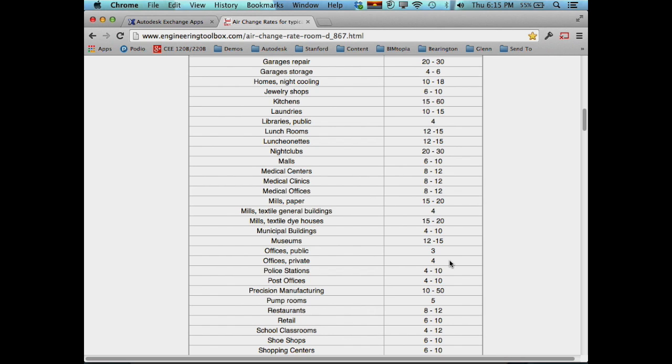You also want to pull away 133 cubic feet per minute. And if everything was super balanced, that would actually work out. It would never be high pressure, it'd never be low pressure. Air would hopefully flow through here. You'll notice as I place these things, I didn't put them right next to each other, because if I put the out right next to the in, what happens is I get a lot of local mixing, but I don't really change the air. So that's not really very good. What I want to do is put the in and the out on opposite sides of the room, if I want air to move through the whole room.